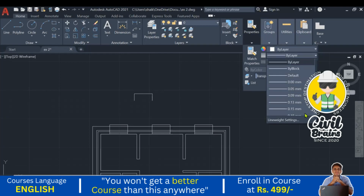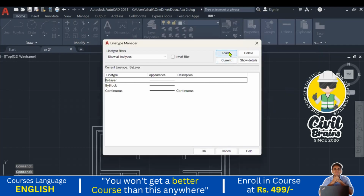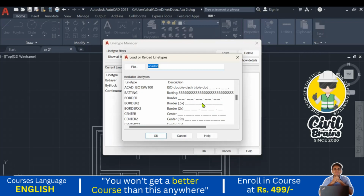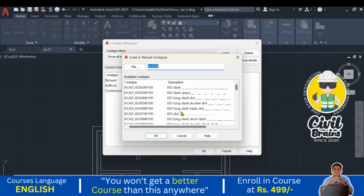Up to 2.11 mm it is there. We don't want to change that one. If you want to change the style of the line, then we need to go here. So you click on by layer, go to other, and here you go to load, and in the load you can see this. So dash line, dash space line, long dash dot line, long dash double dot line. Correct? So there are different lines, dash dash dash dash. According to that, you choose one.